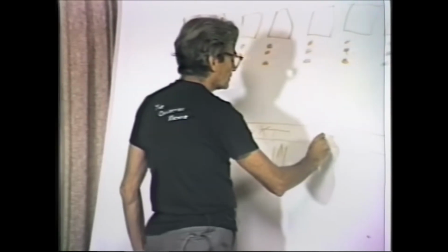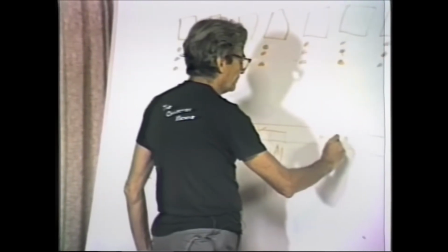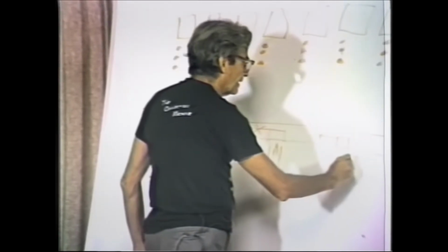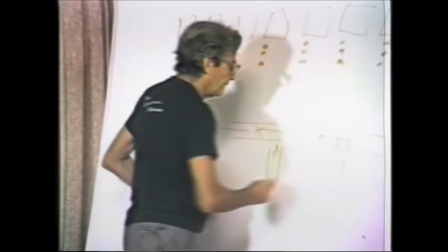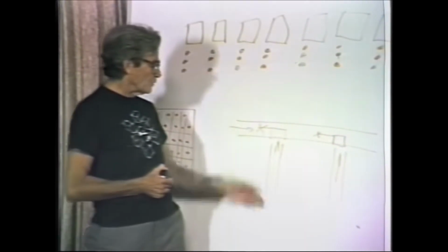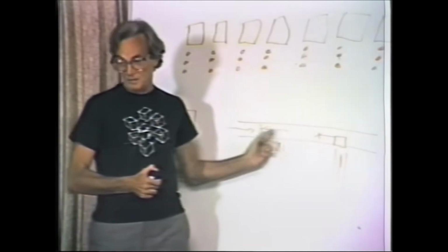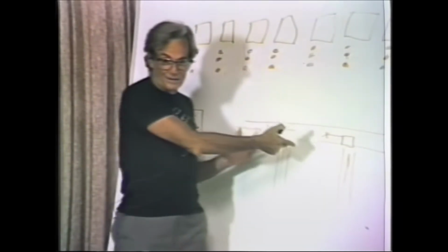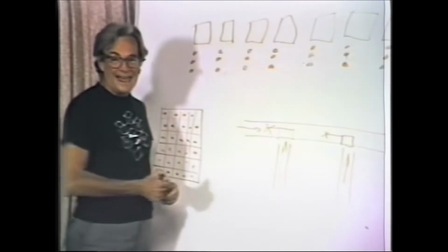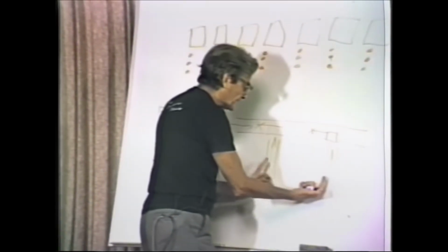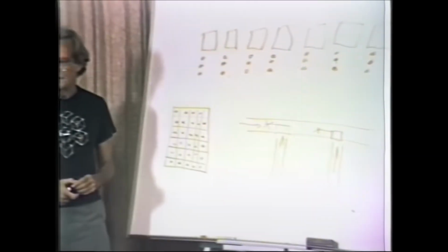Now if I put two such valves in succession in the pipe, and I had the water coming in two different pipes, then it would only work, that is, water will only come out of here if both of these pipes are squirting. Because if I got only one pipe squirting and the other not, this valve is off, but this one is on, so what? It doesn't get through on account of that one being in the way. And vice versa, okay? So this is what you call an AND. You get a result here when both this and that are on.